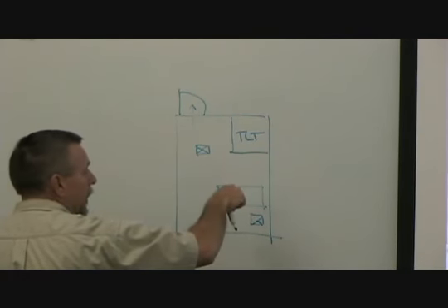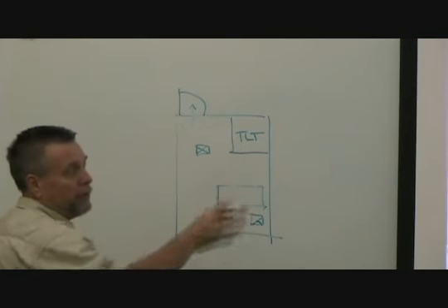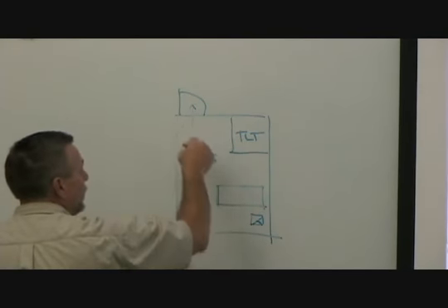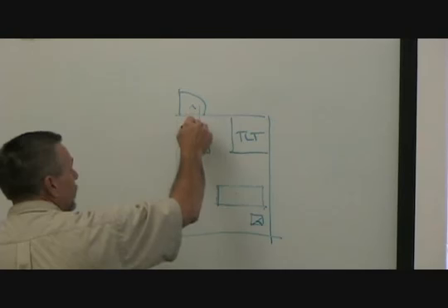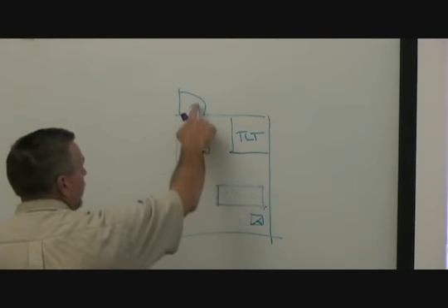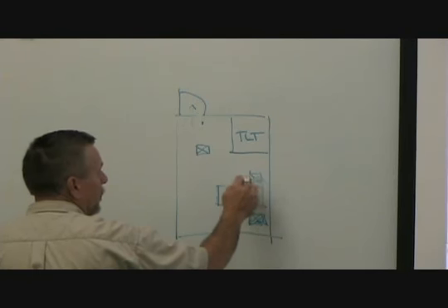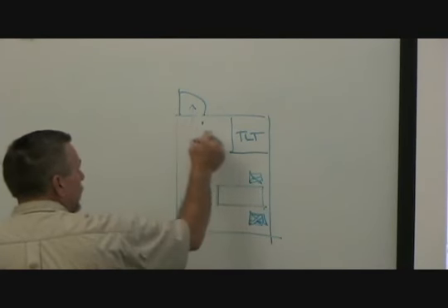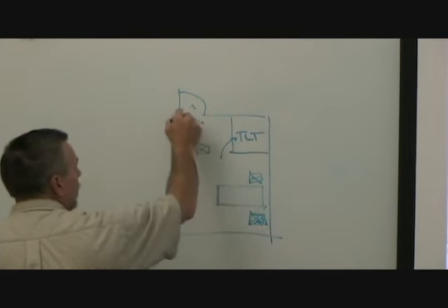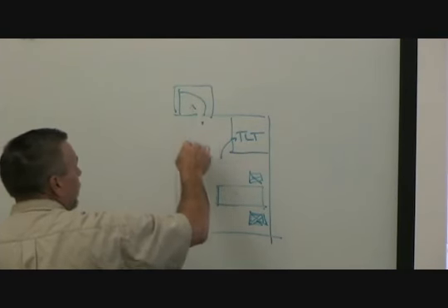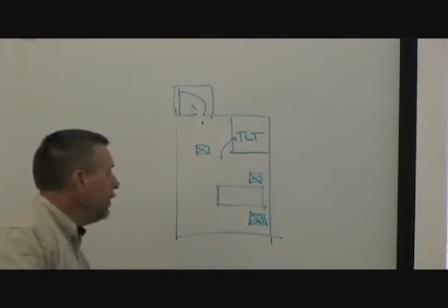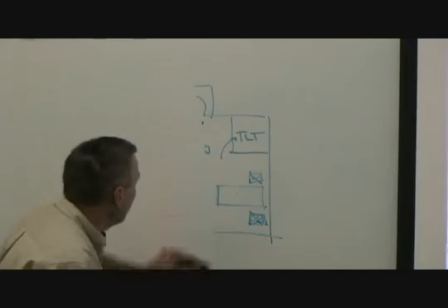In a negative isolation room or typical isolation room that you'd see in a hospital where you're trying to protect, this is a contagious patient, air is going in. And in a protective isolation room, you do just the opposite. Put the supply here over the patient, protect him, and the return goes into the toilet or into an anteroom out here or just some exhaust out here. So those are kind of critical air distribution methods for hospitals that you might want to take note of if you see it.